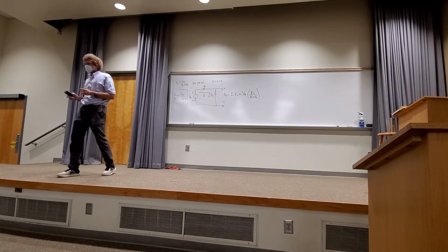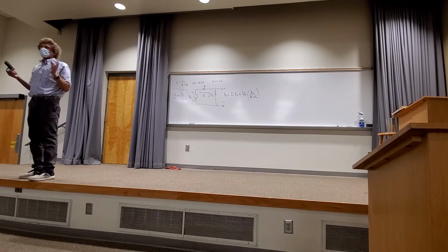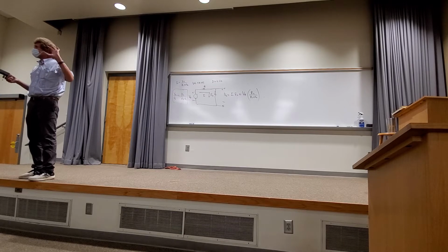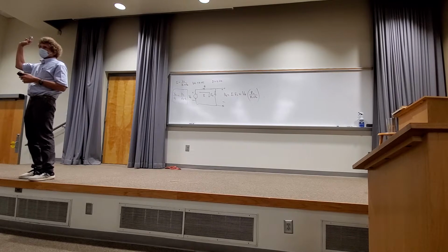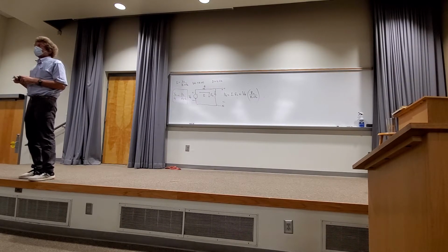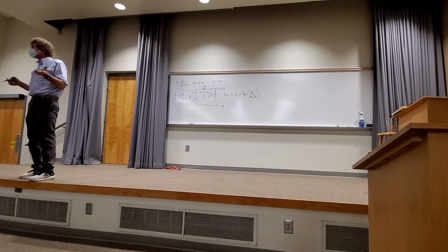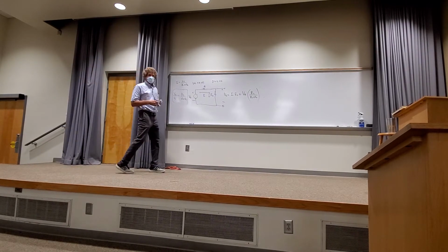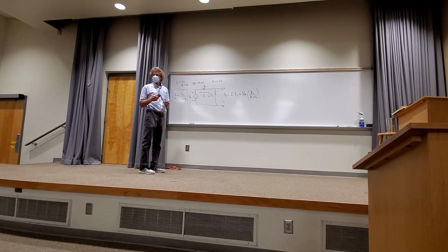If you want the voltage across any resistor and you've got two in series, you just take the source voltage that's across both, multiply it by the resistance you want the voltage across, and divide it by the sum of the resistances. Y'all with me on this? How many have seen this before? You probably saw something like this in physics without ever labeling it, all right? It's a simple reasoning process if you think about it. This is voltage division.